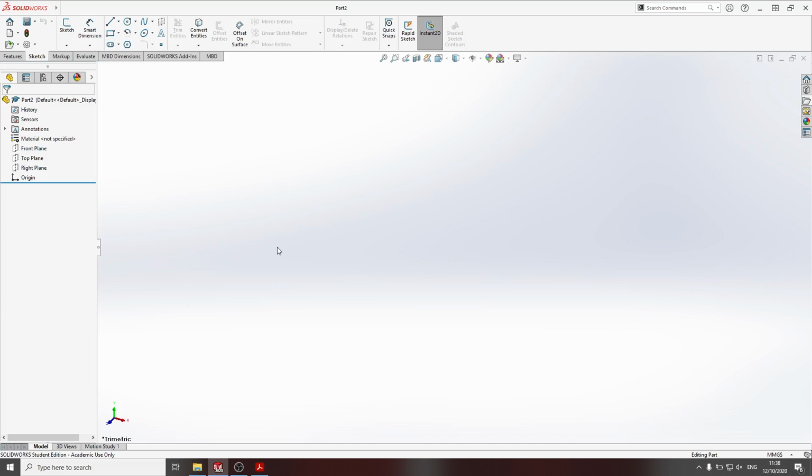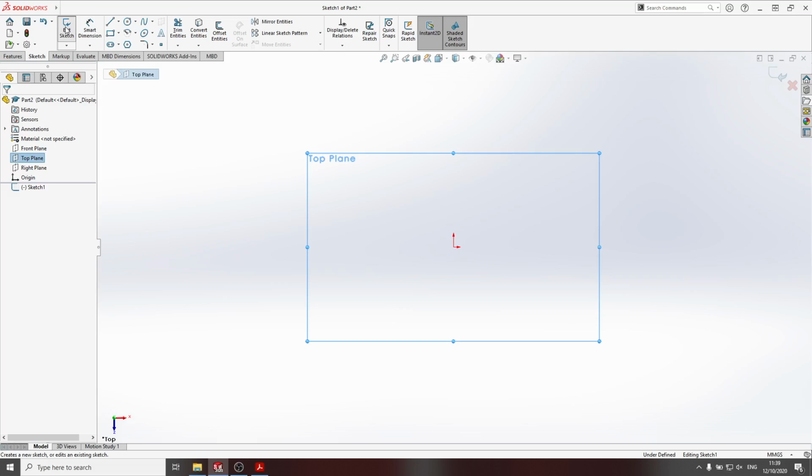The fundamental principle of SolidWorks is that you draw a sketch, mostly a two-dimensional drawing, and then what's called a feature, extrude, for instance, a box out of that sketch. That's what we are going to do right now. I always have to tell where I want to draw the sketch, and I select the top plane right now. In the ribbon I have already selected sketch. Then I go into sketch mode.